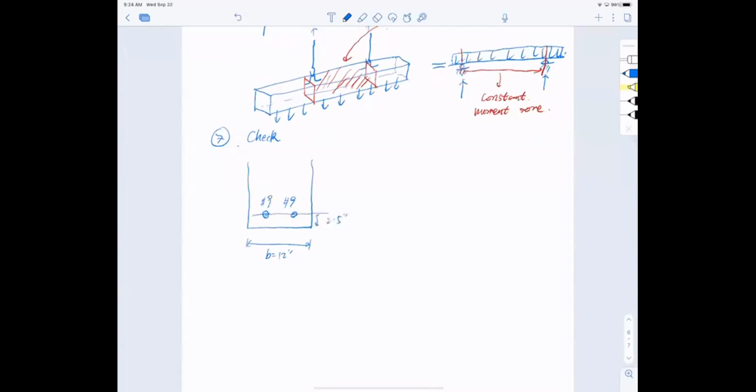That's fine, but is that it? Can I put a bar in? What did I forget to check? You need the stirrups first. Yeah, sure, I need to put the stirrups in. And when you're trying to build the cages or build a beam, you need to lower your reinforcement cage into the formworks, right? So the question is, do you think this will fit in?